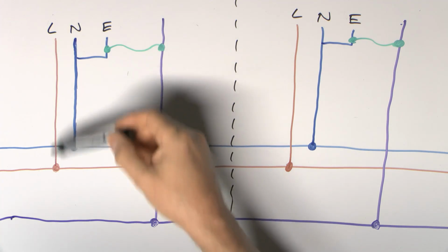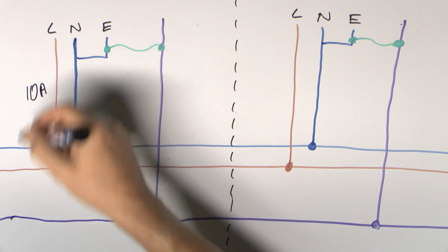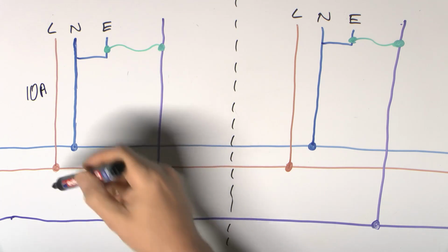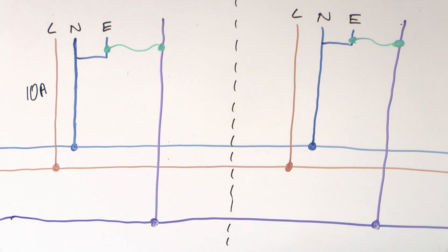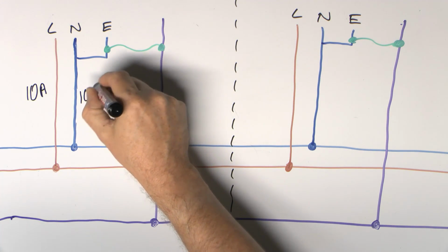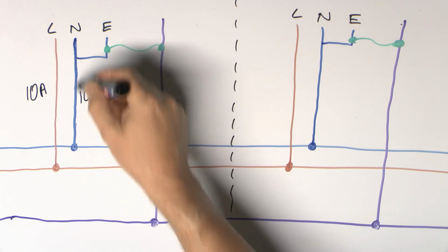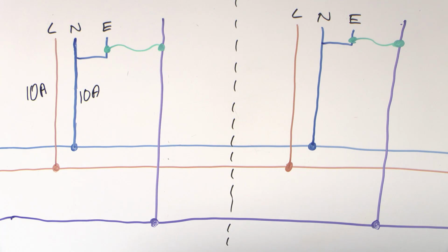So let's say in this particular installation we had say 10 amps coming in here on the line, bearing in mind it's AC so it's theoretically in both directions, but we'll assume it goes in and out here because that's just a bit easier. So 10 amps on the line conductor, and you would expect that there should be around say 10 amps on the neutral or the combined neutral and earth as well, because of course the current is going to be the same on both.